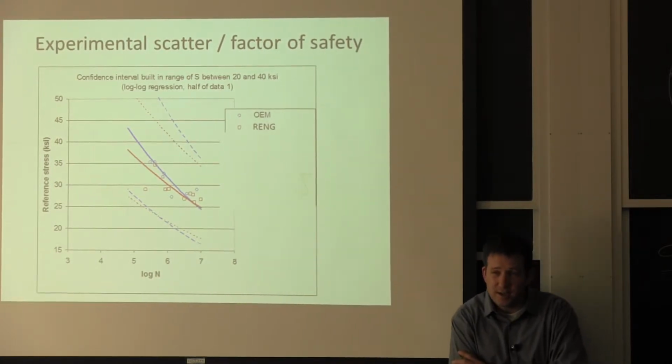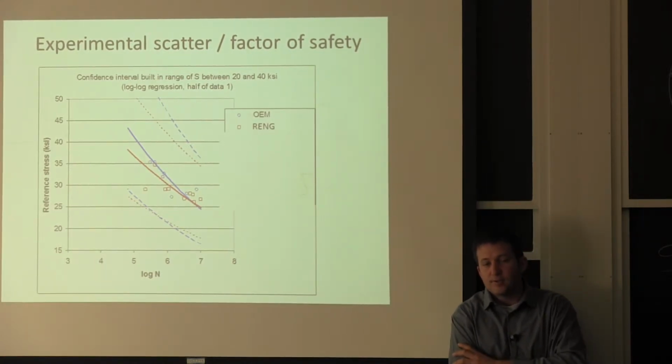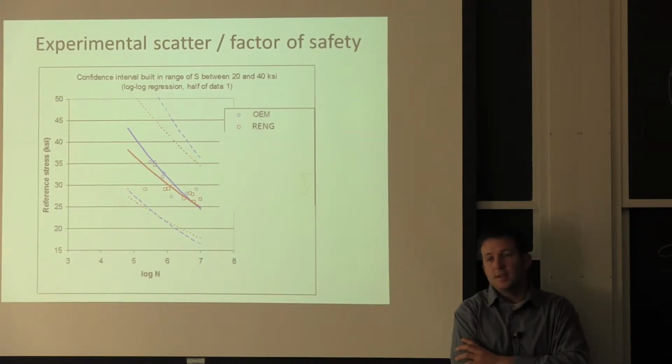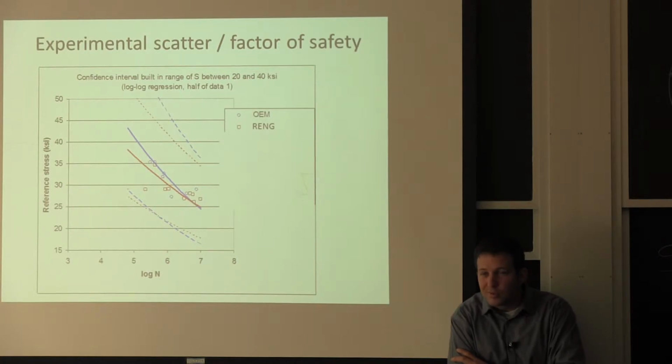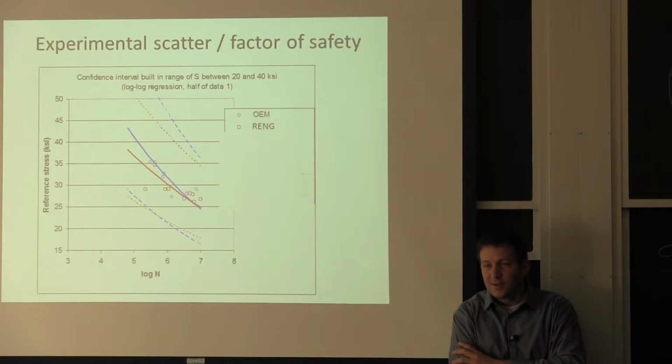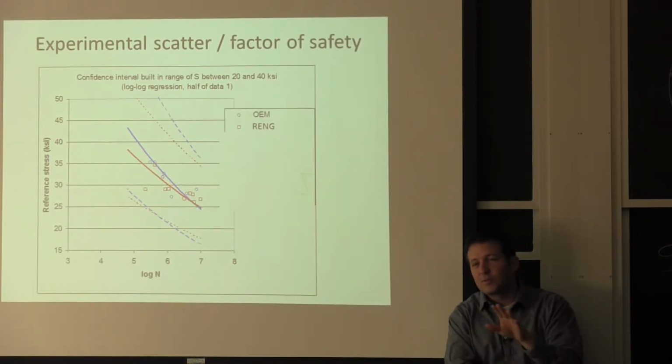If I know I'm going to have high chlorides and a lot of sustained load, and I need things to be very reliable, ceilings of swimming pools, stuff like that, you need to avoid that stress corrosion cracking. You may as well use regular steel that will rust and maybe eventually drip rust through the ceiling, than put something that will look fine and then all of a sudden break one day. That's one example. Just all the building structures.